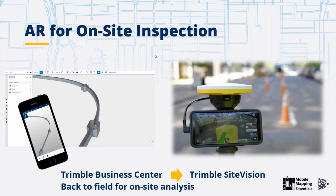It's really dependent on the GNSS coverage conditions. What we do with the MX7 is post-process the trajectory, so the accuracies I'm talking about are post-processed final accuracies, which in many cases could be sufficient.